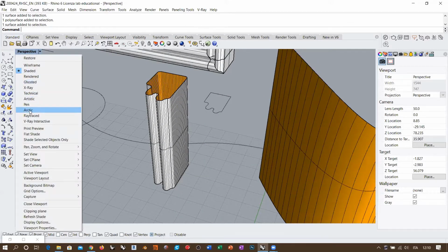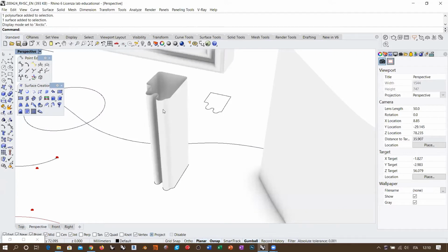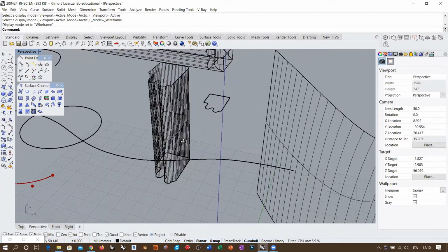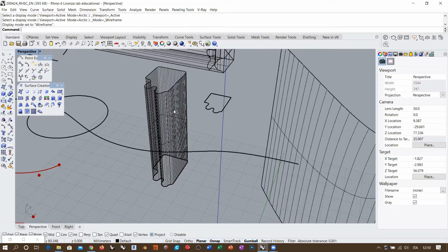If I render this, there is basically no visibility for this internal edge. So it's not a visualization problem. It's a topological problem. So having an edge which is exposed like this basically means that each discontinuous behavior will happen in a visible part of your piece.